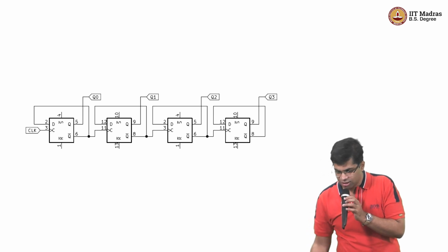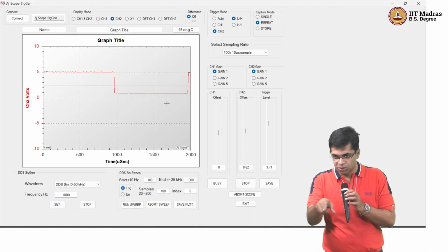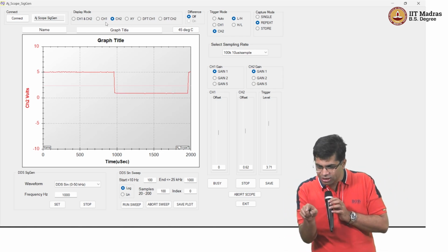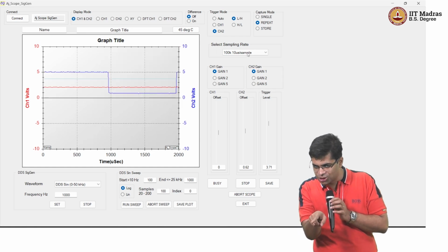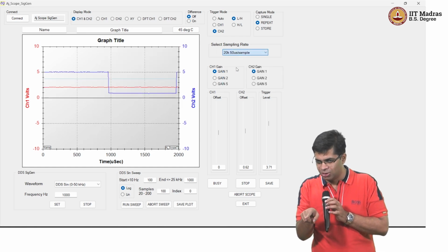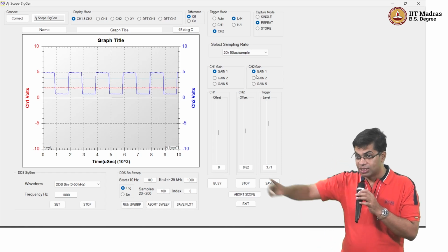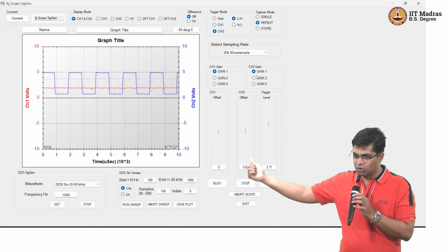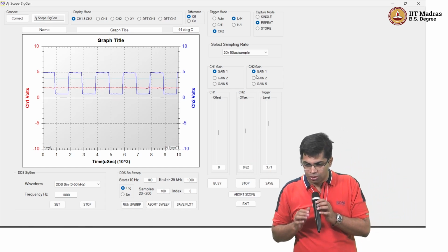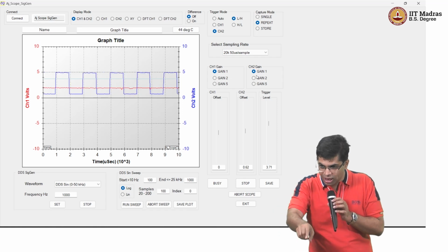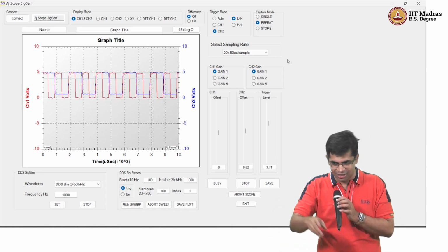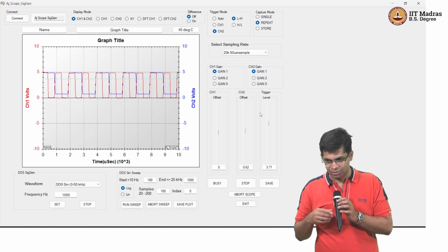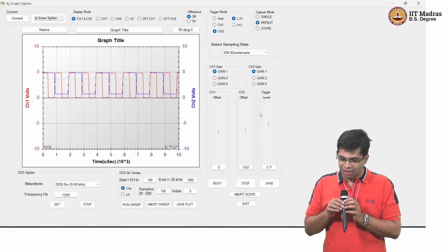See, the signal generator that we have on this version is effectively only one channel, in the sense that the square wave will have the same frequency as your sine wave. The ATXmega version had 2 independent channels. We could not get that to work on this because of the hardware. So if you want a 5 hertz square wave and a 5 hertz sine wave, it will work. But a 1 hertz square wave and a 5 hertz sine wave, you won't get.